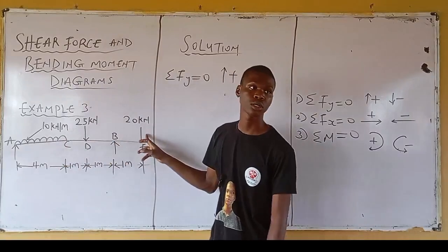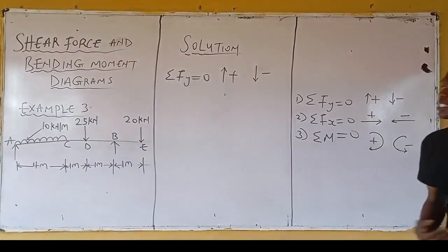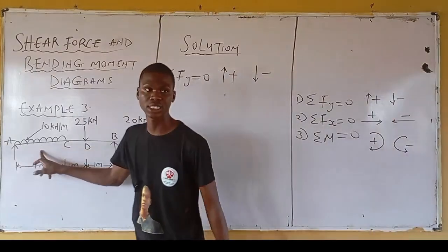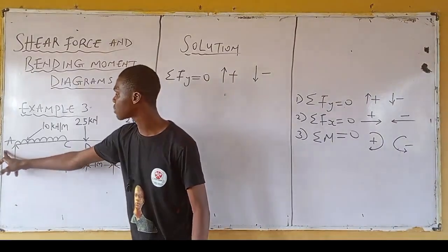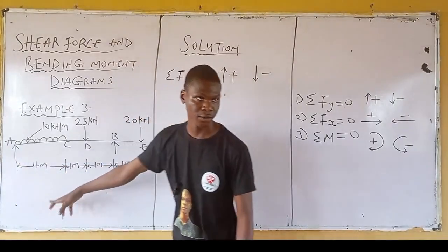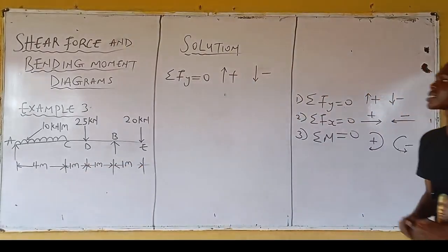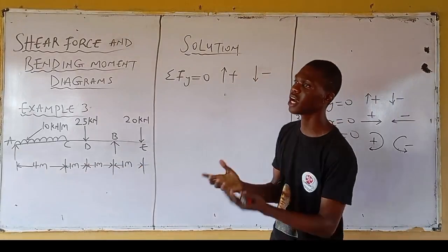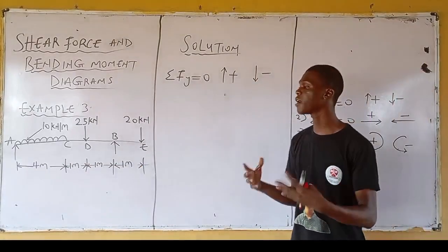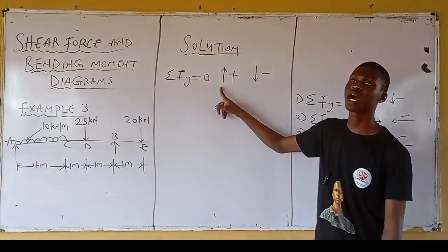these 2 point loads, right? Each load has its respective distance, though it is only the UDL that has a distance. Your UDL is spanning from A to C. It is covering what distance? 4 meters. Now we've identified that I have 5 forces. Now the question is, how many forces of this nature do you have and how many forces of this nature do you have?